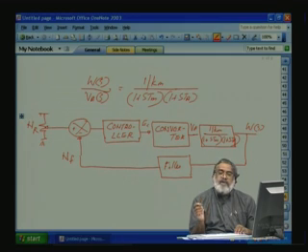So we want full speed, the machine is at standstill and we are giving full voltage. So what will happen? There is no back EMF. If you go back to our previous equation, the armature voltage and armature current, back EMF is not there. So the full applied voltage has to be dropped across the resistance and the leakage inductance.